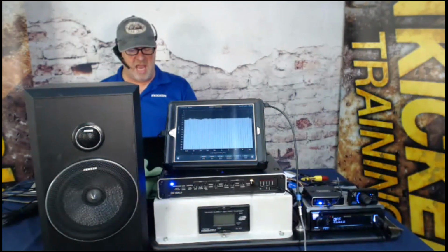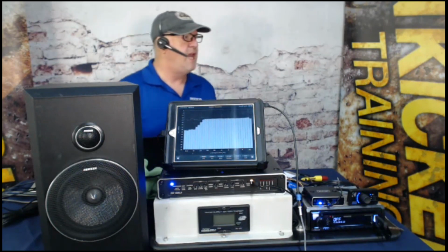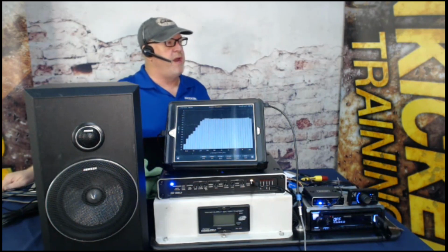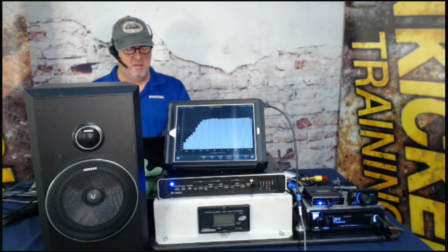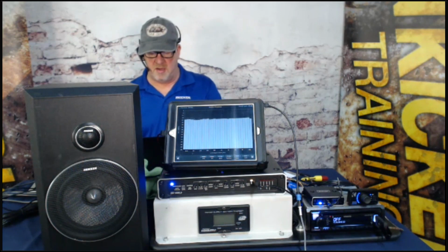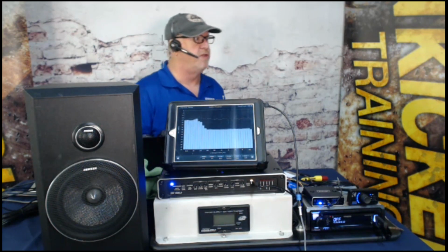So let's go ahead and turn on a high pass crossover at 24 dB per octave. Now, if you notice what's happening to that graph, that is showing a high pass crossover at 150 hertz. Let's go back to a full range signal. Once again, usable full range signal. Let's go turn on another crossover. Let's turn on a low crossover.